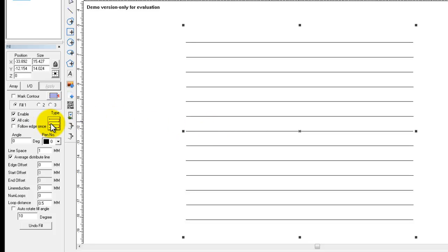So, as a representation for this fill type, over here you can see that the blue is on, which is this. This line represents being on, means the laser is going to process it. When it turns the corner to come up and process this next line, it's going to turn itself off. So there's no laser marking happening between this line and this line. It's just going to continue down, it's going to turn off and come back and continue down again.